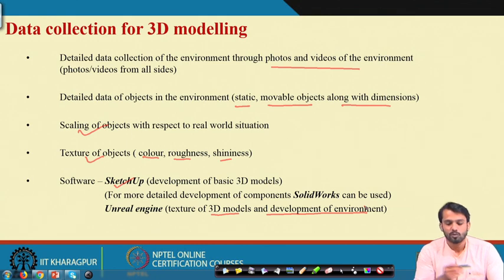workplace, you just place this 3D laser scanner in that workplace, and it will automatically scan the workplace by rotating 360 degrees, and it will give you the output in the form of point clouds. You just have to join the point clouds using the requisite software, and directly you can create the 3D model. In this process, the time required for photo and video collection and the time required for the generation of 3D models using different 3D modeling software can be reduced. Directly you can create the 3D models with the help of joining these point clouds.